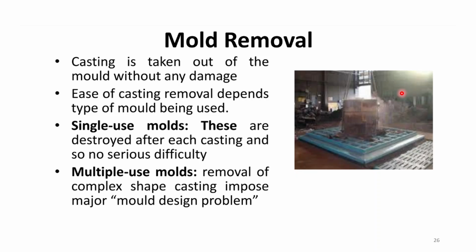The ease of casting removal depends on the type of mold being used. It can be either a single use mold or a multiple use mold. In case of a single use mold, these are destroyed after each casting, so there is no serious difficulty in removal of the casting. With multiple use molds, you have to take care that your mold doesn't get damaged and your casting also doesn't get damaged, so it is more complicated. The removal of complex shape castings imposes a major mold design problem.